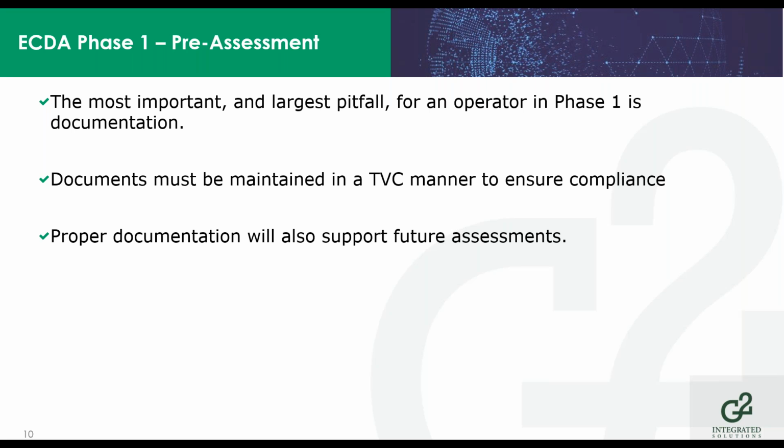Pre-assessment, and this goes for all phases, should generate a report which documents any decisions, all of your data collection, and feasibility determination. If you have any missing data, that should be documented also. You should also make sure that your pre-assessment report defines what your regions are, using maps, station numbering, mileposts, or some sort of means to determine where your regions start and stop. So that's the pre-assessment phase. Again, it's a lot of office work and document review, but a good pre-assessment phase will set you up for the rest of the project.